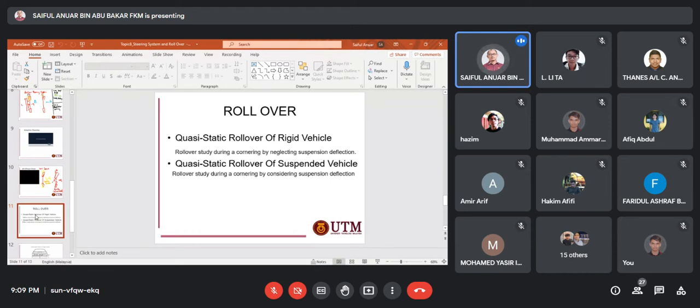The only thing that causes the car to move down when you press hard on the corner is the deflection of the tire. You need to remember the tire also acts as a spring, so that's the only source of deflection. Other than that, the hard suspension won't move at all because it's too stiff. This is typically preferred by racing drivers.